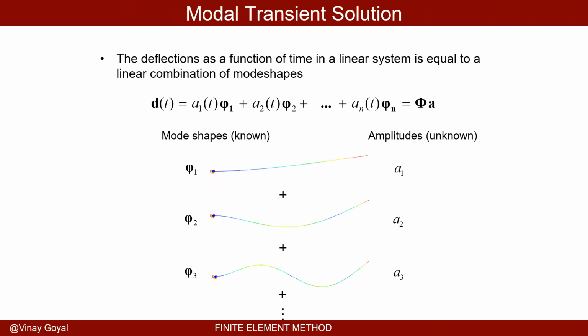And that's very powerful. Say I have a rocket that has millions of degrees of freedom. So I have millions of eigenvalues and mode shapes, and if I have to use all of them to describe the motion of that rocket, that's computationally expensive. But what if I told you that perhaps I want to worry about mode shapes below 150 hertz? That'll truncate the number of modes I have to consider, and that'll make this problem a lot more tractable.